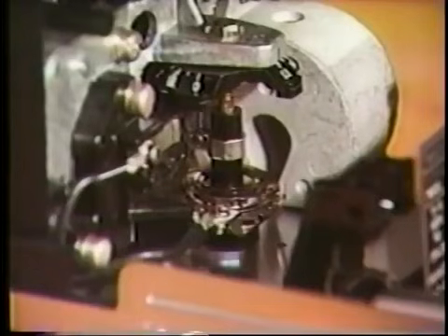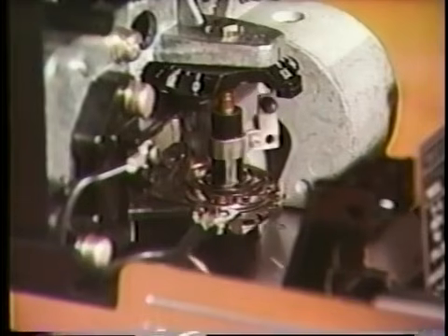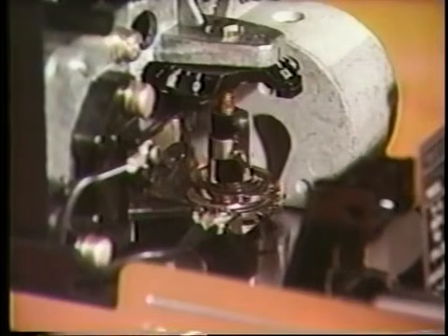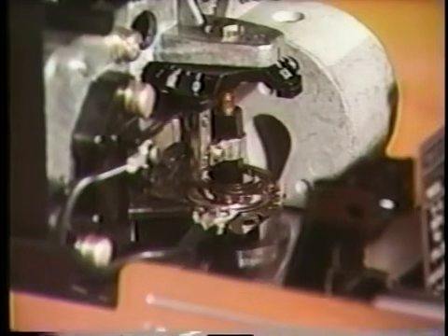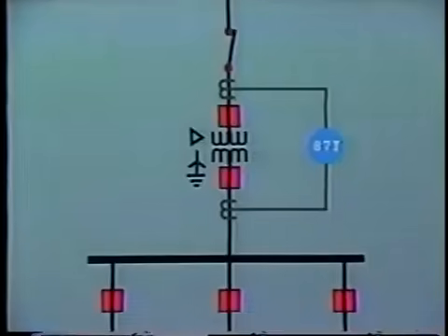The operating element consists of an induction disc. This operates quite slowly, about 0.1 seconds, so it will not be responsive to the short-term inrush current. In yet another method for preventing tripping due to inrush, the operating coil of the differential relay is desensitized for a few milliseconds when the primary breaker is closed.